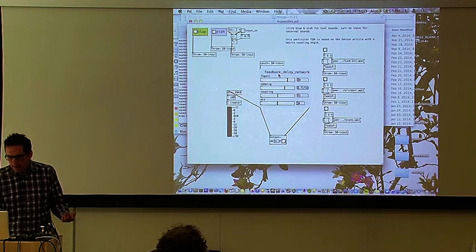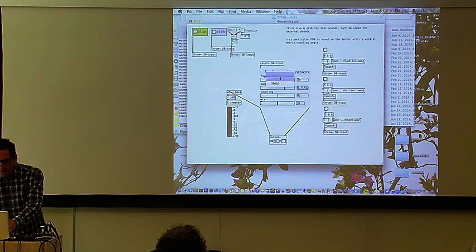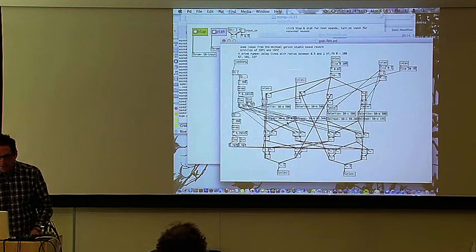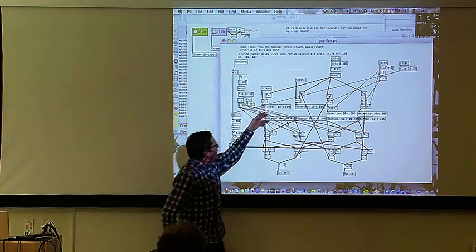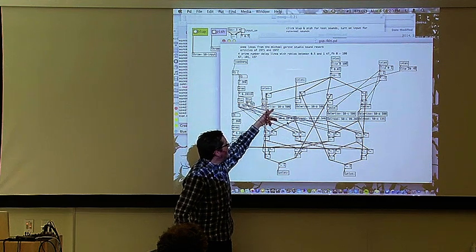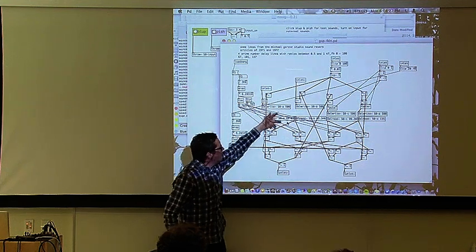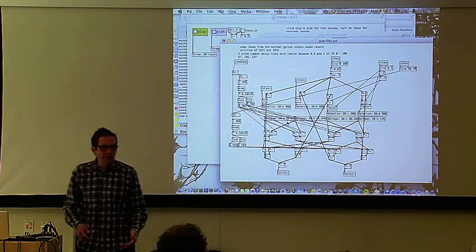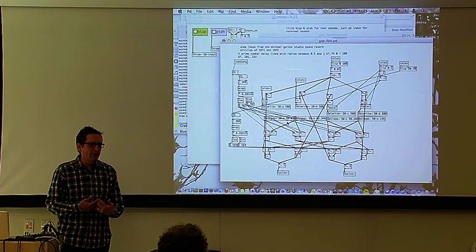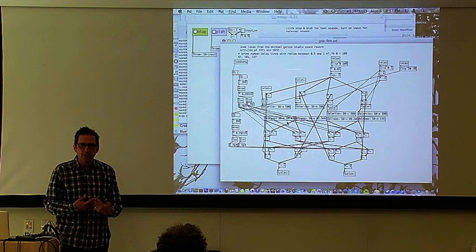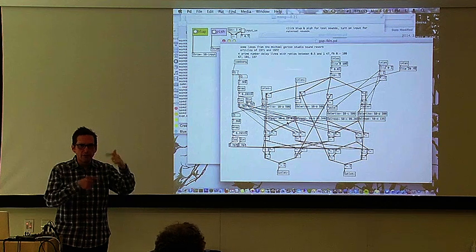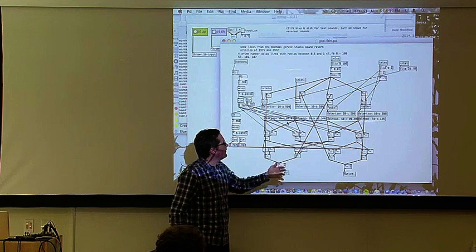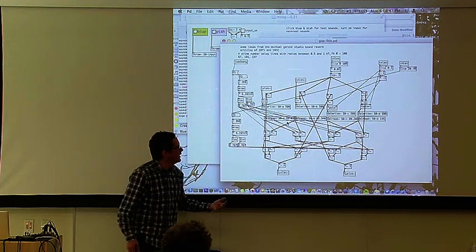And the difference between this and, say, Schroeder's design, and the difference between Chris Moore's design, is really the simplicity. We're only using 4 delay lines for this reverb, which is not much at all. Even the Schroeder design used several all-pass filters, which are really feed-forward feedback delay lines, and a number of delay lines. Chris Moore's design used many more delay lines.